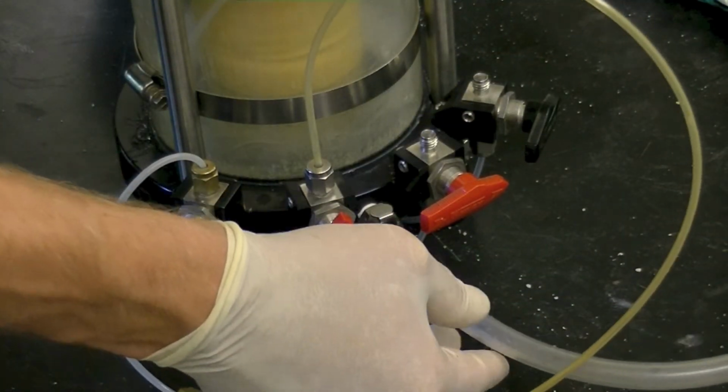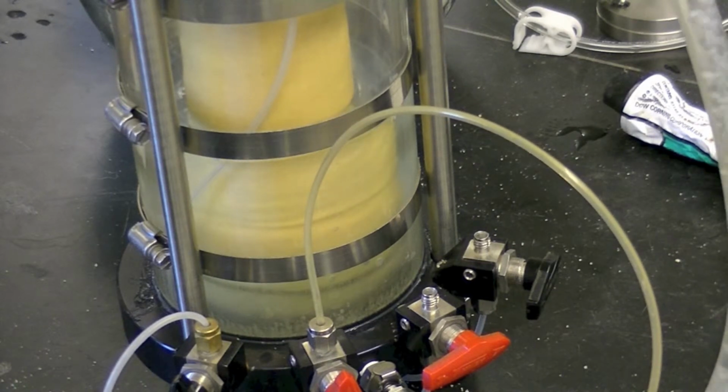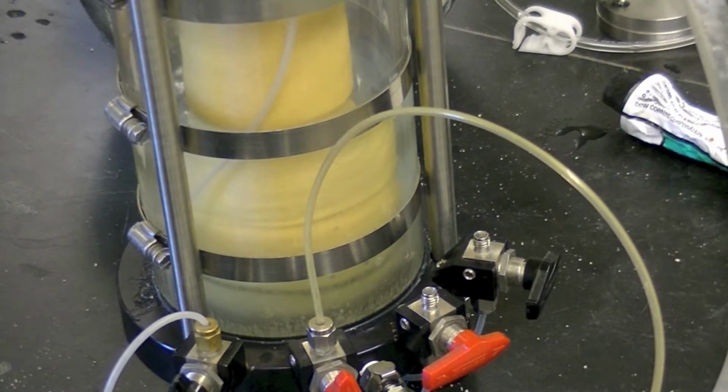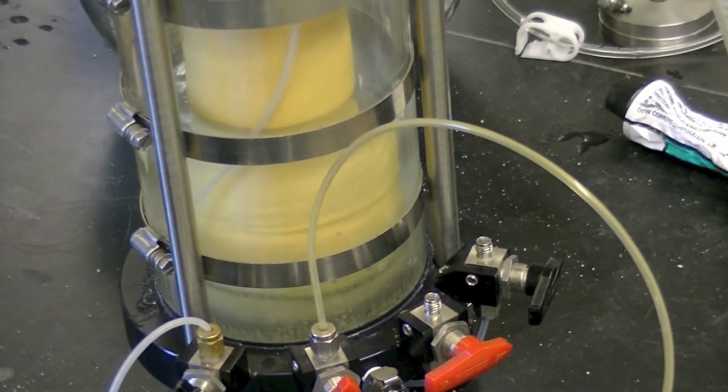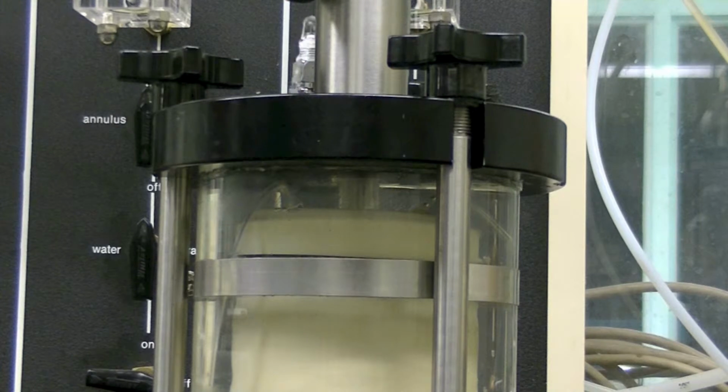Connect the fill valve with the fill hose. Fill the chamber completely with de-aired water. An air release should be open at the top of the chamber to ensure the chamber is completely filled with water. Once water begins to come out of the release, close the air release valve, and turn off the fill water and the vacuum.